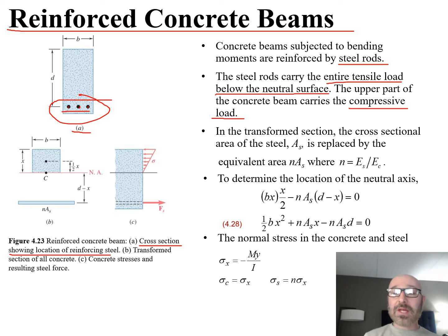Now in reality, this is a simplified version of this. There's multiple layers of rebar, and you've got to think, because it's also wide. It's not just 1D. You have multiple dimensions of a concrete bridge deck. So this is more of a girder situation right here, rather than an entire bridge deck where you have rebar running crisscrossed over top of each other at different layers if you're dealing with an actual concrete bridge deck. So just a side note to make it more realistic for future applications when we're actually putting rebar on the bridges.